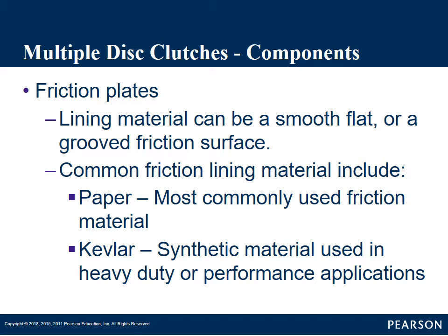The grooves in those friction materials allow fluid to flow through. It helps while it's applying. It keeps it cooler, because remember, we're taking friction devices and pushing them against steel devices. That's going to create heat and friction as they apply, and that fluid is meant to go through those grooves to help smooth that application and cut down on the heat that's produced. It's like a lubricant in this apply process.